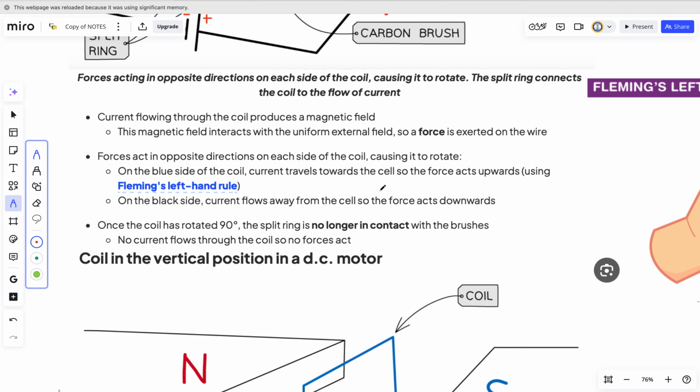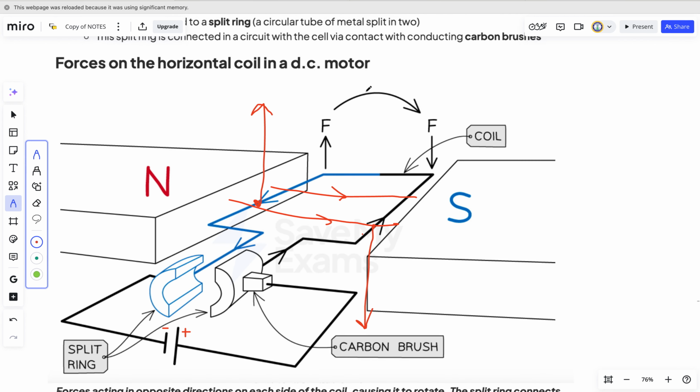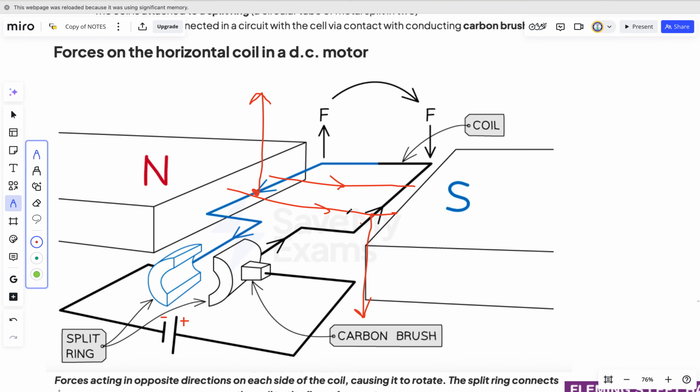The magnet itself produces a magnetic field because you have a north pole and south pole. The magnet itself is the external magnetic field. And then the current-carrying wire also produces a magnetic field. These two fields interact with each other to create a force. The force, or thrust, or motion, is going to happen on both sides of the rectangular array of coils, and when that happens, it will cause rotation of this rectangular array together with the slip ring commutator.